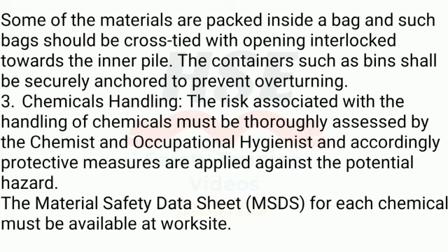Some of the materials are packed inside a bag and such bags should be cross-tied with opening interlocked towards the inner pile. The containers such as bins shall be securely anchored to prevent overturning.